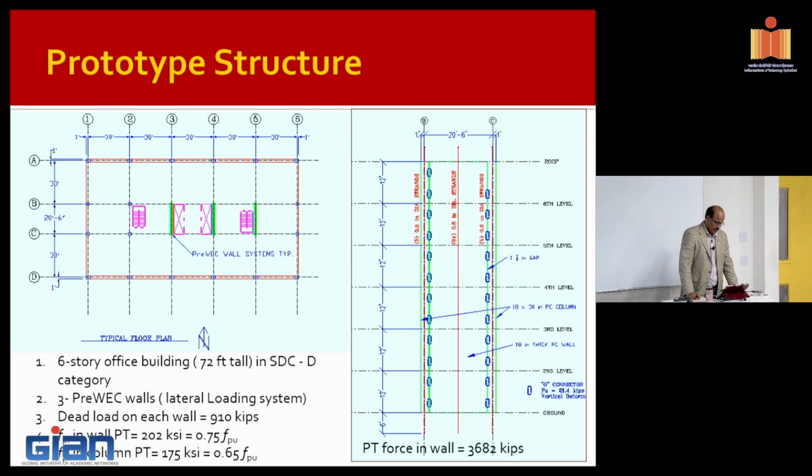So, if you say you have, pick a number, say 1500 kilonewton, lateral force that you need to resist. Then for that 6-story structure, you could choose to resist that particular load through a frame structure or a wall structure.